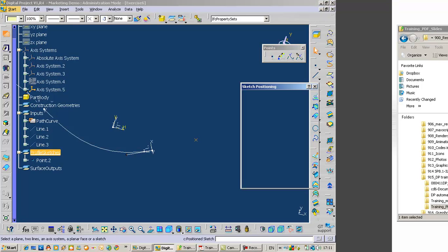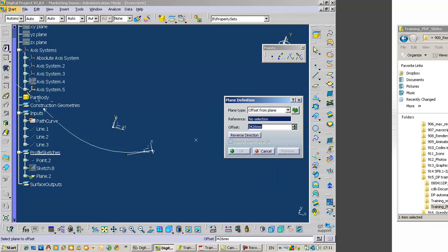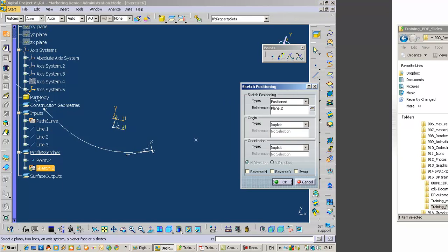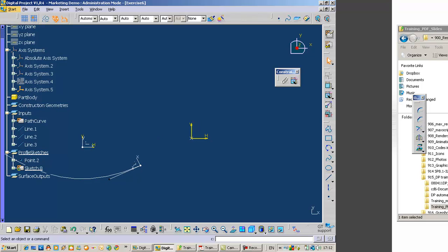So once I create a sketch, this time I create a plane. I select x, y. That's okay. Change the origin to projection point, and then pick this point. You see that H and V are created on the projection point to the sketch plane. Click OK. Okay. Now if I draw the shape, actually I already copied, so I just paste.